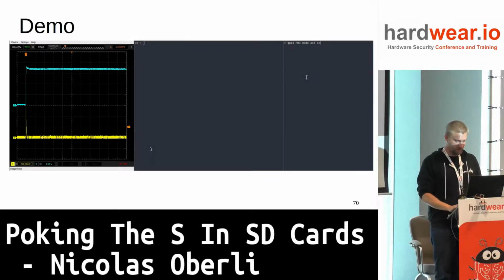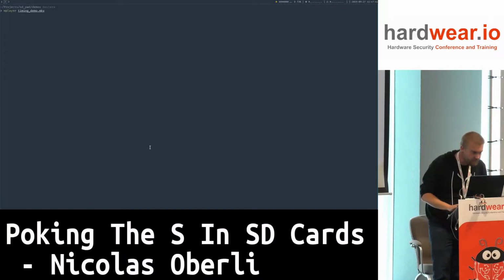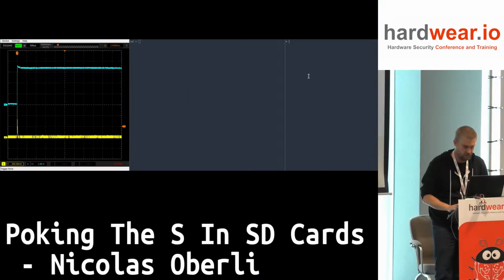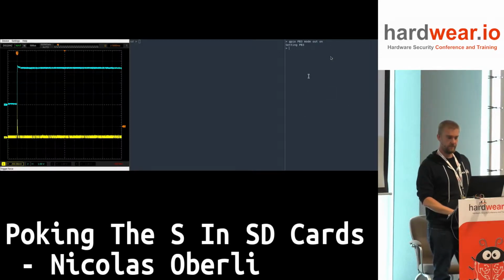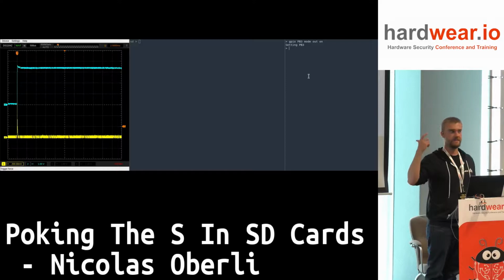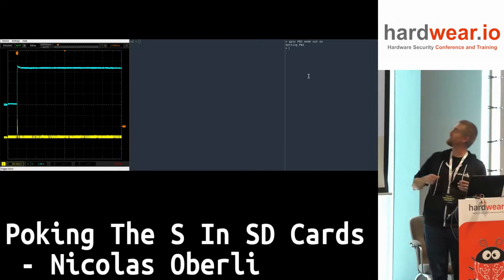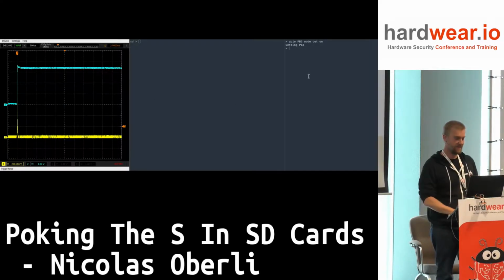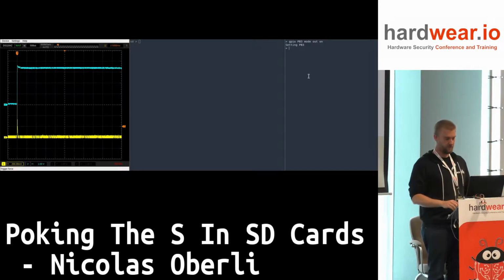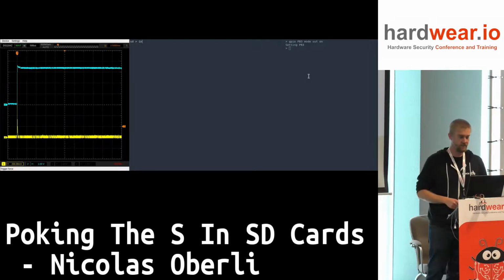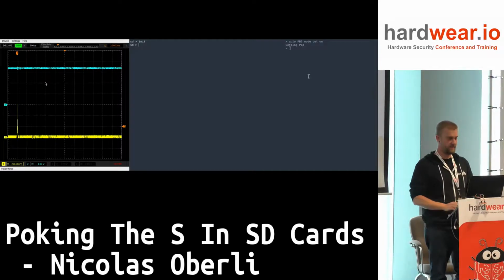And to show you how it works, I have a demo video that I can show you, and we'll try to comment on it live, if it's possible. On the right here, we have the HydraBus that is doing the triggering. It's a bit small, sorry, but the fun part is this one. In the middle, you have my SD tool that will basically send the clear command to the card. And on the right, you have the output of the oscilloscope.